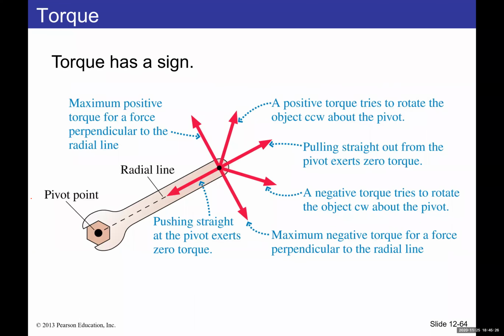Okay, so here you can see that, for example, let's call these 1, 2, 3, 4, 5, and 6. So you have 6 different forces acting on this wrench, and you want to know the torque from each. So let's say torque 1. Well, torque 1 will be, if I'm looking at this, here's the distance r. So it will be r times f1. Since all of them have the same exact distance r, it's r times f1. And since it's perpendicular, the sine of phi is 1, so it's r times f1. That's torque 1.